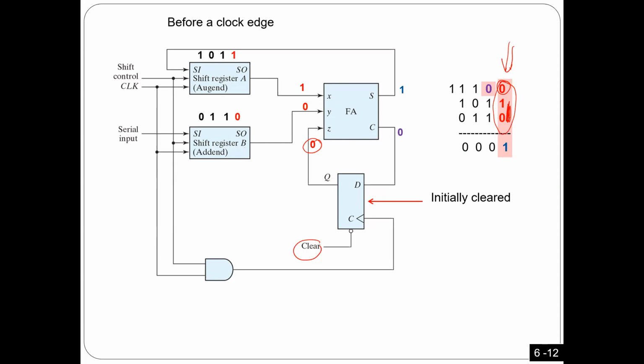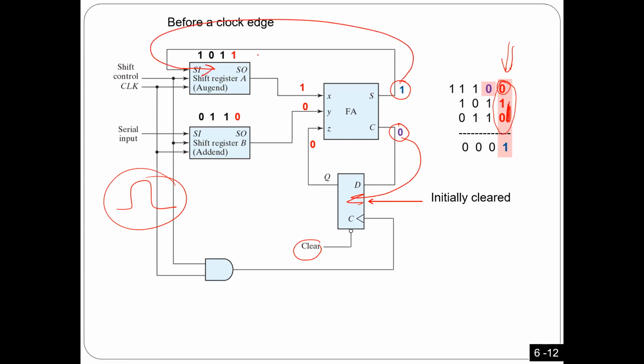So what you can see here is, because this is a shift register, I have 1 here, 0 here, and then 0 coming from here. If you do the addition, the result is 1, and the carry is 0. Is that okay? Then after the first clock, so I need 1 clock, after the first clock, this 0 is going to be stored here because I need it in the next 2-bit addition. And this one, which is a part of the result, is going to come here. This one is gone, so I'm going to shift. So these 2 are gone. That's exactly what I'm showing here.